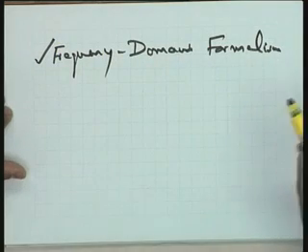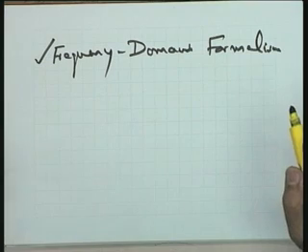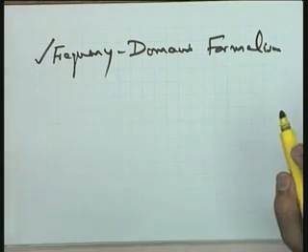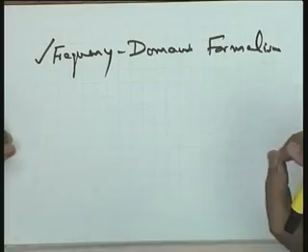I will say that as far as the present stage of analysis and design of control systems is concerned, you consider the root locus method, you consider frequency domain, or you consider other advanced methods which you have not studied, like the state feedback pole placement, like the optimal control. Probably the most often used is the frequency domain formalism. The reason is this, that this gives, as it is said, the robust control. The dependence of the frequency domain methods on the model of the system is not that stringent as that of any other method, including root locus.